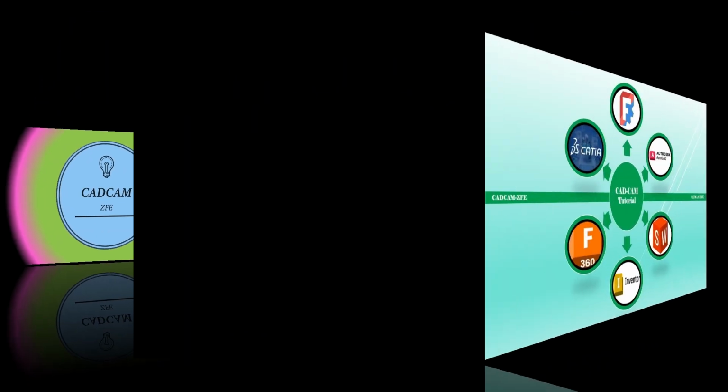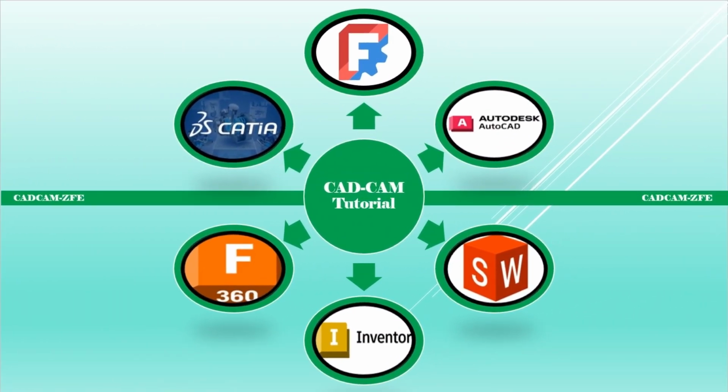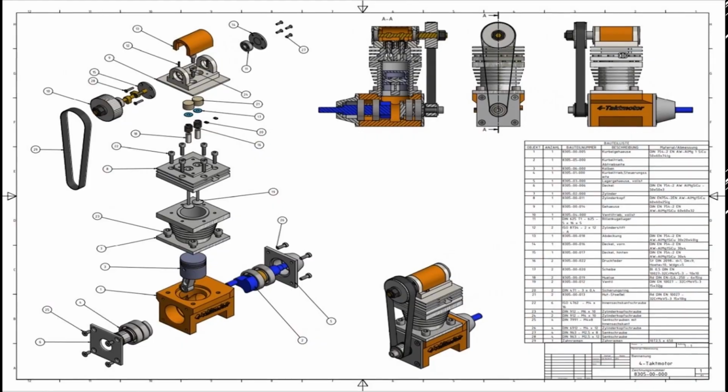Today I will show you how to create a 3D model from the existing 2D drawing with the help of FreeCAD tools like Extrude, Hole, Polar Pattern, and Fillet.